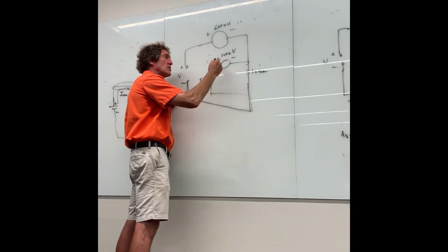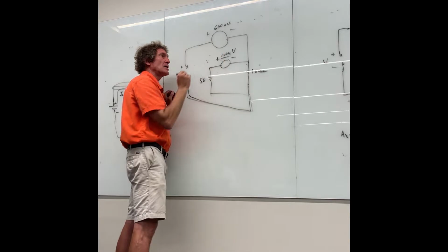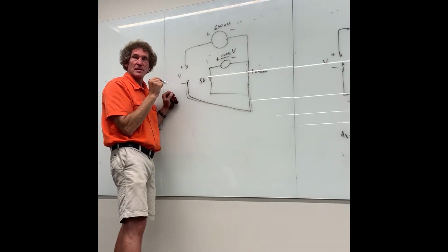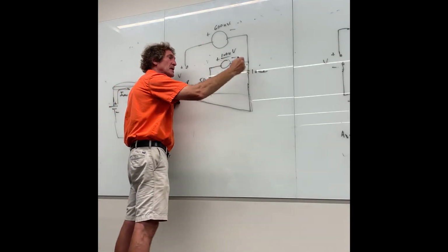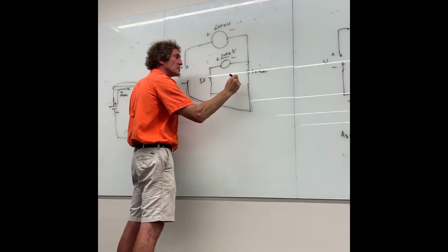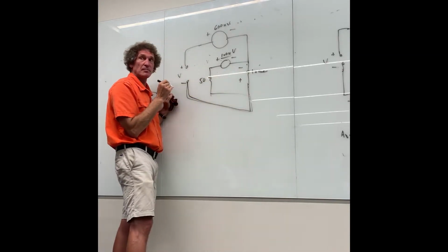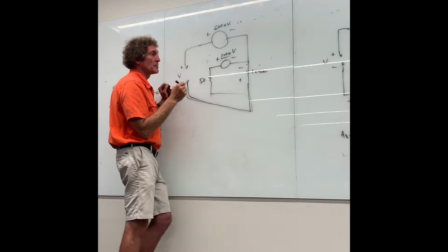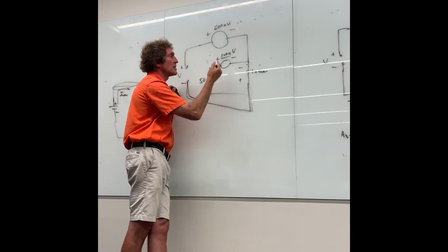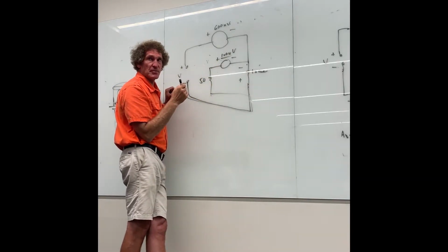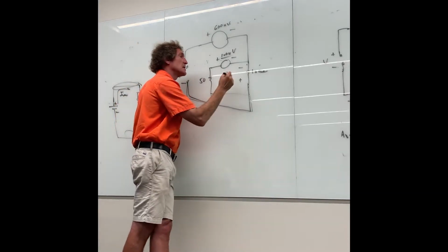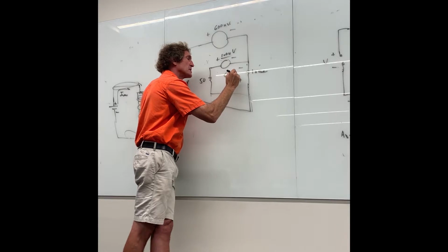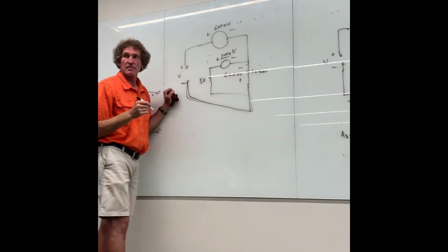You see how in this closed loop right here, we have 100 microvolts, right? And it's being divided between 50 and 100. So what would this voltage be here? It would be plus to minus, right? And it would be 100 over 150 times 100 microvolts. Do you agree with me there, class? That would be 66 microvolts, isn't it, class? So this would be 66.6 microvolts. Agreed?